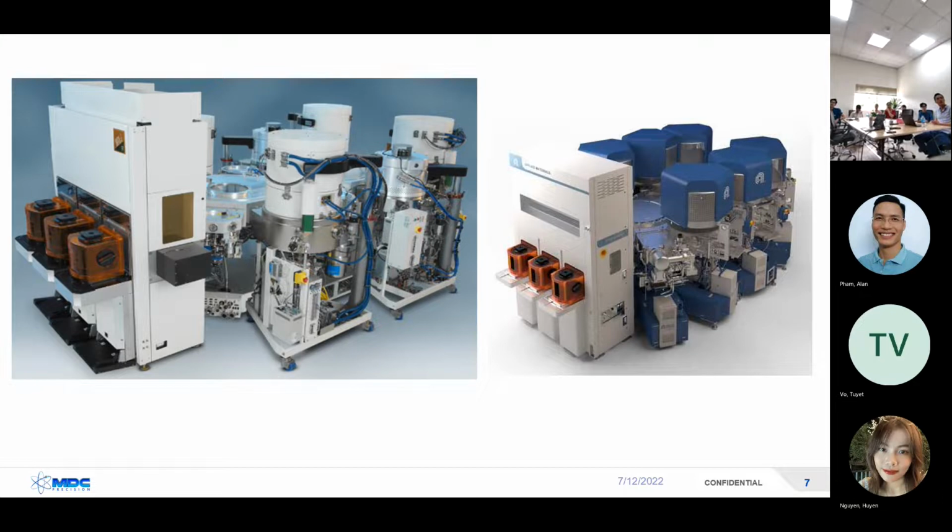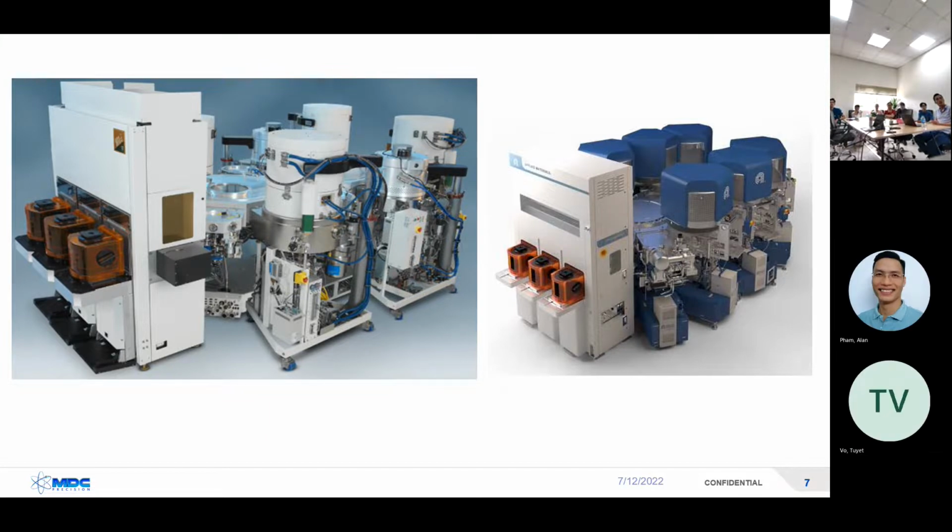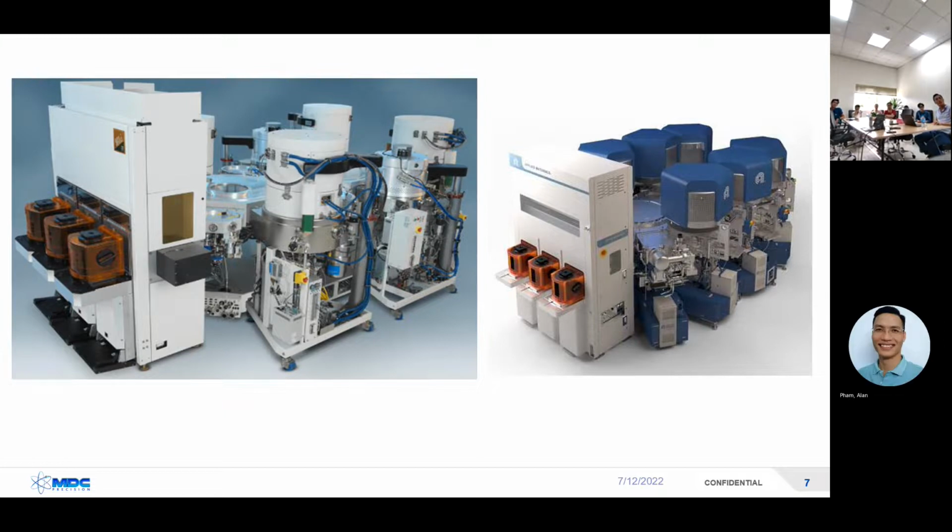So we take the wafer from here. All this is just robotics to move into these chambers. Okay. So the wafers go in and this would now be in vacuum, it's called. So this would be kind of equal to the vacuum at maybe 60,000 feet in the air here. So you're in the early part of space. This is typically about maybe 10 to the minus 9. Okay. Then, once you get this all set, the wafers go into this processing chamber, which again will start in a deeper vacuum, 10 to the minus 4.